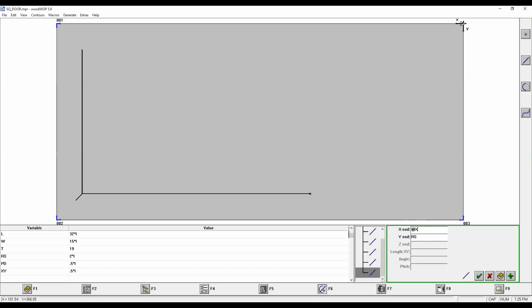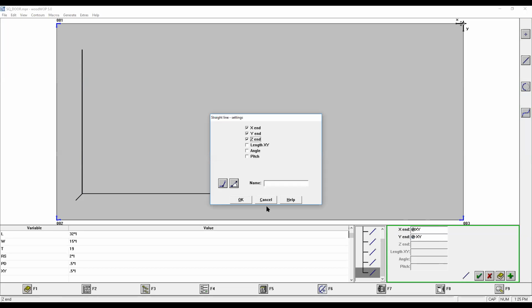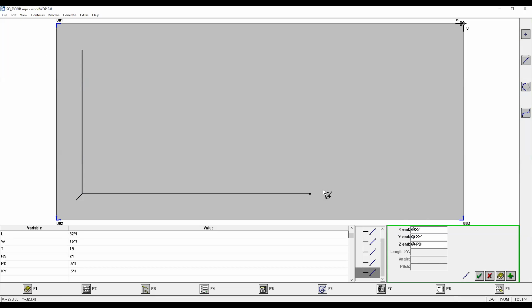So at minus XY, and we have to turn on Z. Z is a dangerous move, and the program wants to make sure that you physically go in and pick it. Otherwise, it would show up all the time and you could forget what you were doing, which could be dangerous for the tooling on the machine. So now we came up in Z, copy and paste.